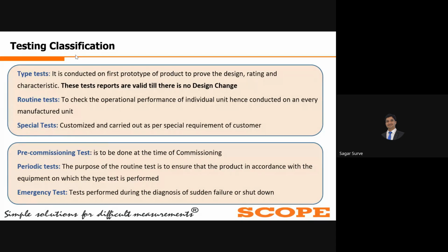These tests are conducted by government recognized or national and international labs. From there we have to get the certificate that our transformer has passed all these tests. These test reports are valid as long as there are no design related changes inside the transformer. If you have some design changes in the transformer, you have to conduct the type test again for this new design.